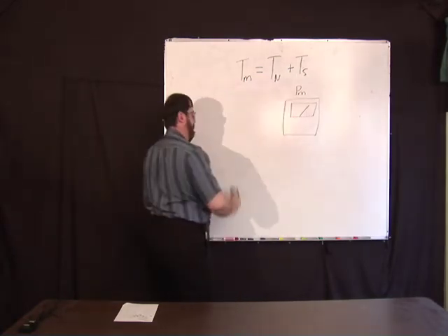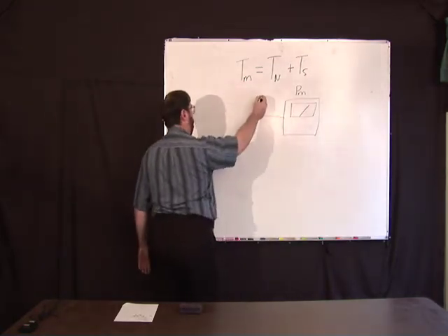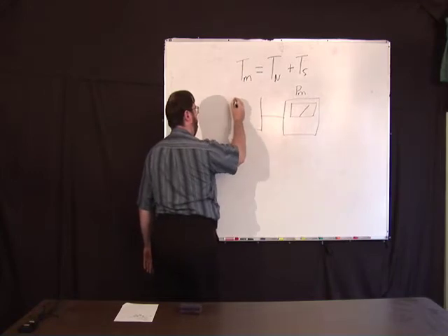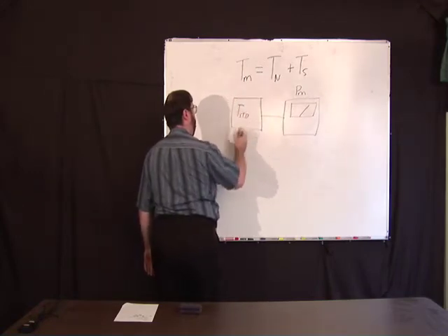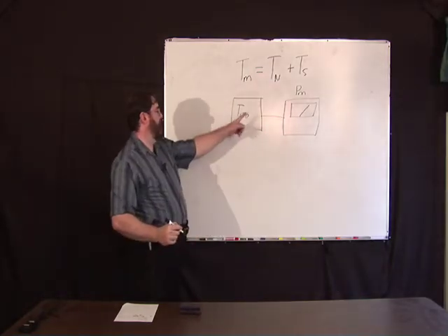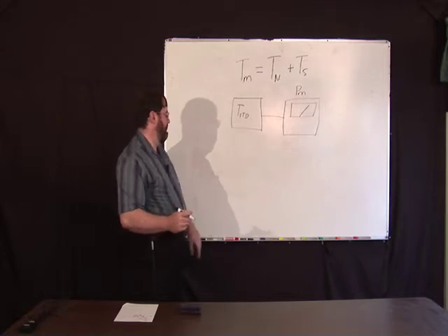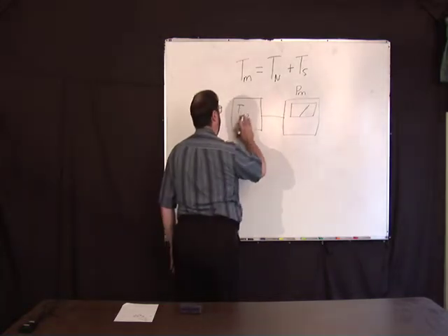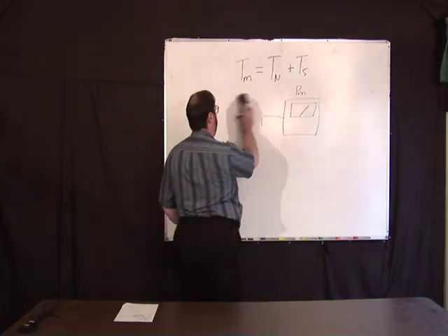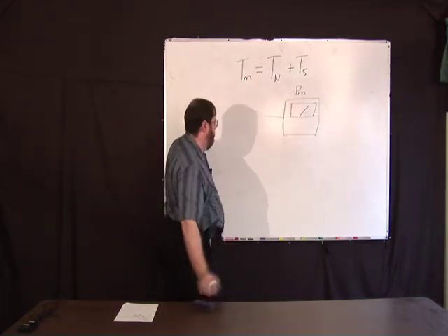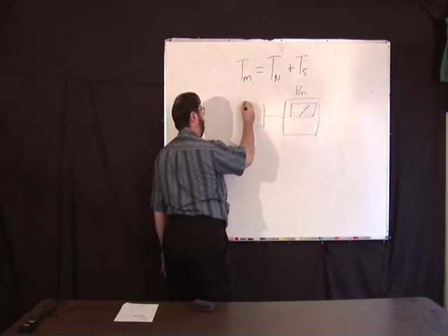Well, one way to do that in your measurement system is to deal with a known standard. You could have a T standard, and you could measure the noise and subtract them, but that's typically not how it's done. Typically, and there are all kinds of reasons for that, mainly the system noise temperature changes with time.